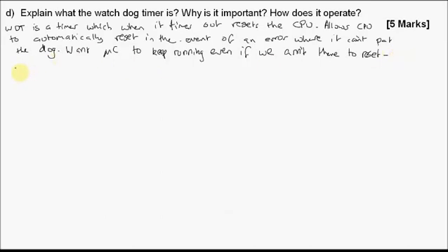And how does it operate? We periodically pat the watchdog. Basically we set the timer, the watchdog timer value is reset. And if we don't pat the watchdog, it will time out and reset the CPU.